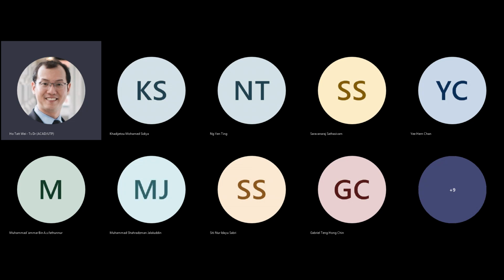That insulating region is not something you put in, is not a dielectric. It just arises from the fact that you have an N-type material bordering a P-type material. Automatically, there is a charge-free region that forms at the interface. This acts as a capacitance. So at this part of the gate, this part here, that appears to be a capacitance sitting here, just as there appears to be a capacitance also sitting here.